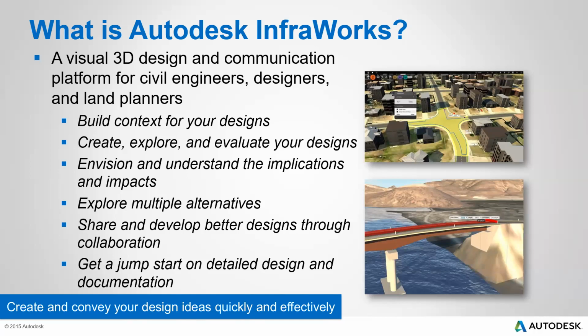With Infraworks, you can tell the performance of your road. You can even run some analysis in terms of the passing sight distances, stopping sight distances, okay? So that you'll be able to know if I were to use a speed of 80 kilometers per hour, at what particular sections of the road should I have these particular traffic control measures based on the analysis that you have performed. So it enables you to do some level of detailed design. You can apply design criteria and be able to know the performance of your road based on that particular design standard that you are going to use.